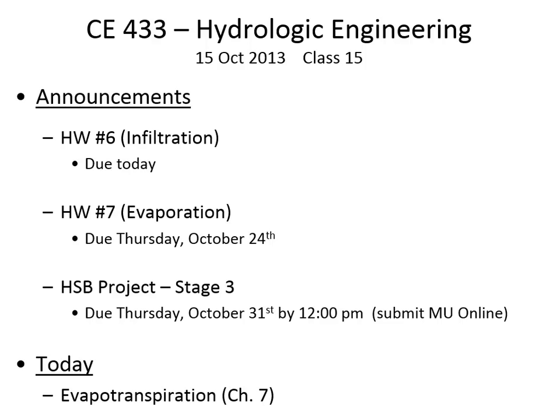What we're going to be talking about today is evapotranspiration, and the text makes the point that the magnitude of evapotranspiration is oftentimes very small for a watershed, and I'm going to make the point that it's extremely difficult to model evapotranspiration. So this aspect of the hydrologic process has the distinction of both being maybe the least significant and the hardest to measure. But that varies depending on where you are. In some watersheds, evapotranspiration is a very small part of the overall water balance. In other watersheds, it's a huge component.